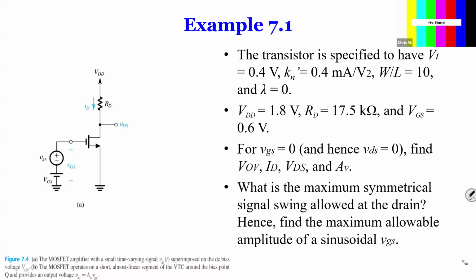They know that there's a DC, but the DC doesn't do anything to the AC except provide biasing. So we simply neglect it, saying, okay, we know that's a DC, but it doesn't do anything to AC anyway. So you're going to see some of the circuits that don't have this one, but they always say that's a small signal equivalent circuit.